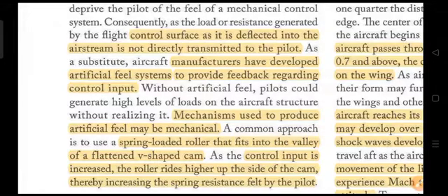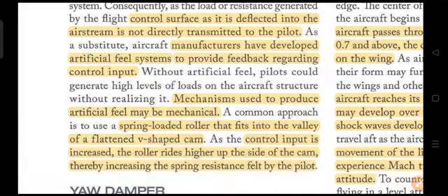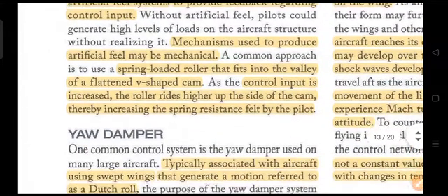That is the reason the force on the control surface, as it is deflected into the airstream, is not directly transmitted to the pilot. The manufacturers have developed an artificial feel system to provide this feedback regarding the control unit. So you can feel it when you are pushing the trimming switch right or left. When you trim too much, you will feel too much resistance in moving the switch, which means you have moved it too much, right? That is a feel you can get in your arms and fingers while moving the switches and controls.